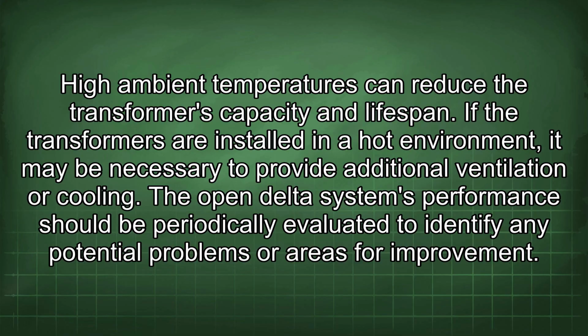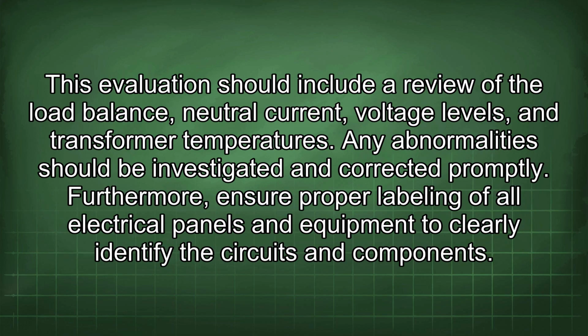The open delta system's performance should be periodically evaluated to identify any potential problems or areas for improvement. This evaluation should include a review of the load balance, neutral current, voltage levels, and transformer temperatures. Any abnormality should be investigated and corrected promptly.